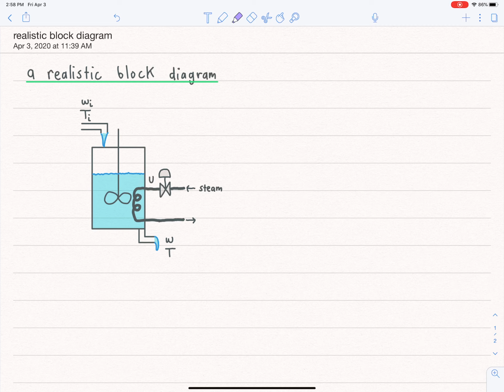And to do that, we feed steam through this pipe, and the pipe is fed through the reactor, and it's coiled around to increase the surface area of contact between the surface of the pipe and the liquid. And there's steam flowing on the inside of the pipe, and that keeps the pipe very hot, and then heat transfer occurs from the pipe walls to the fluid in the reactor, and that is what heats it up. So this is a liquid heater.